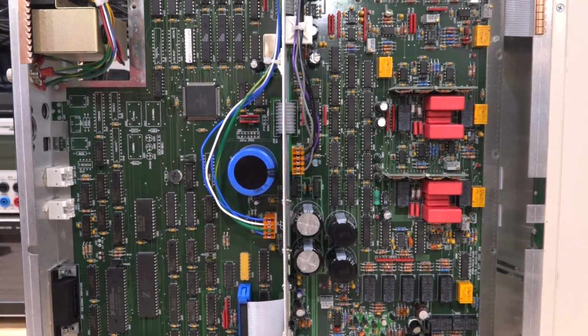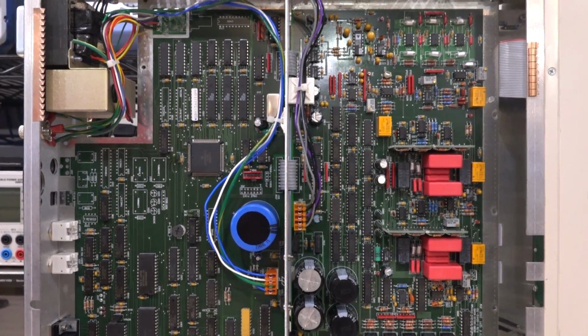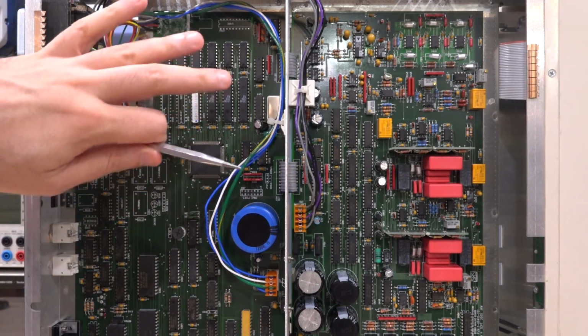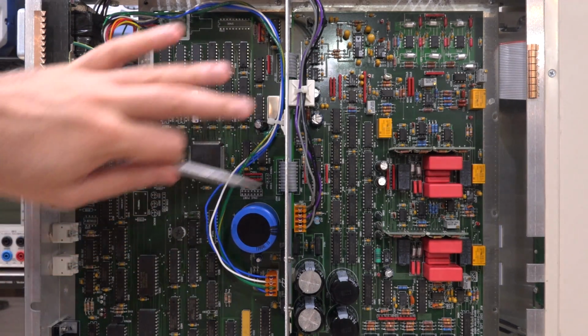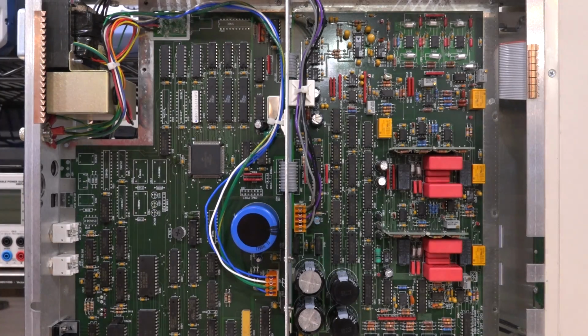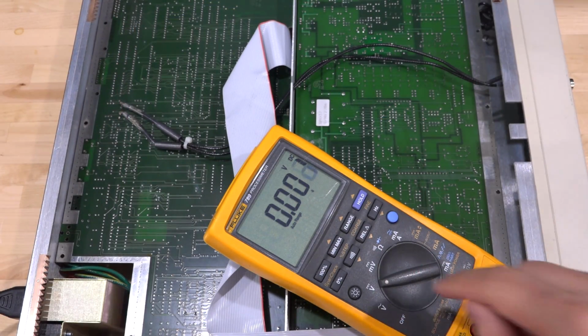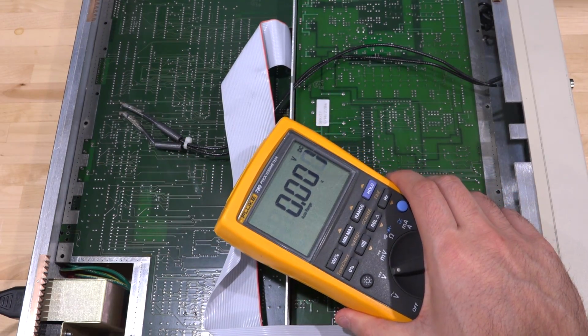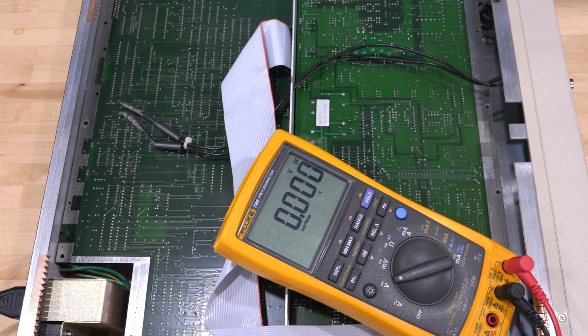So now we have a good idea of the architecture of this. We should follow through and see if we can make some critical measurements and see what happens to the digital signal generated in here and how it finds its way onto this side. And let's check the power supply using the Fluke 7089, which I repaired in the previous video. We can measure the power supplies directly on the capacitor voltages.